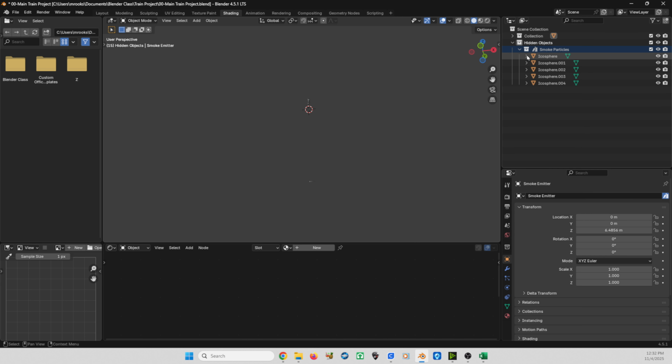and they're going to be part of that group. So we do not want the particles showing up or us accidentally selecting them, or even them hiding and unhiding with other things. So we're going to go to this check mark, which will prevent them from being seen at all. Even if we hide or unhide things, they'll stay more hidden than other objects. Okay.